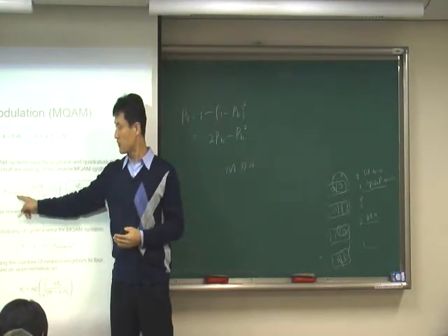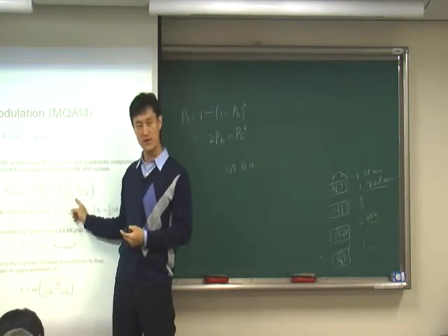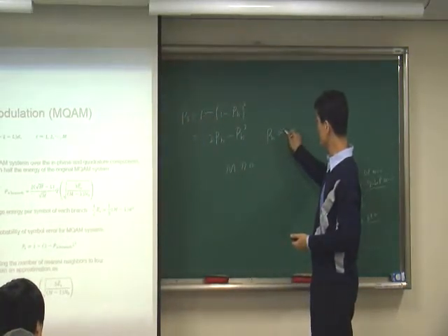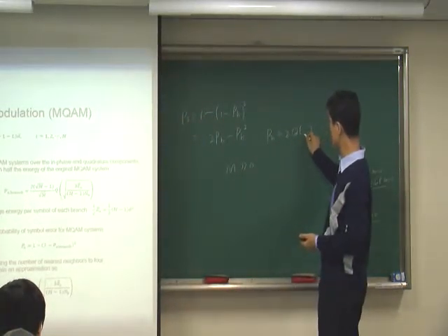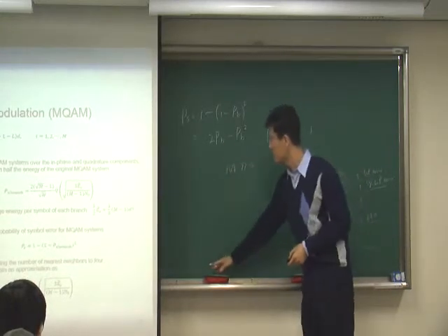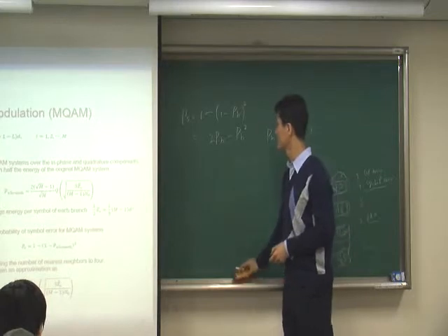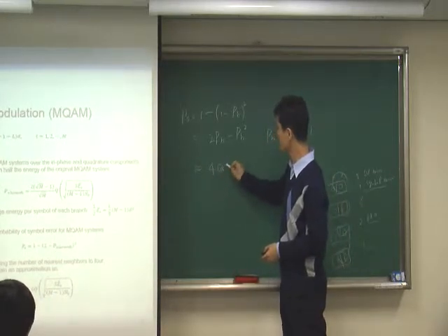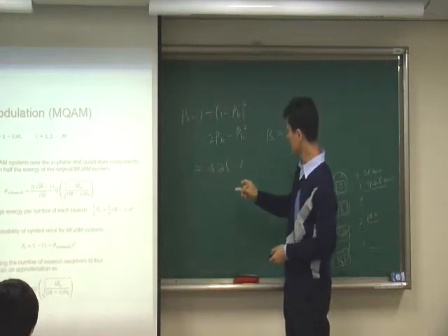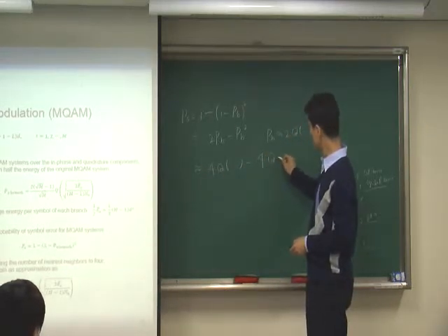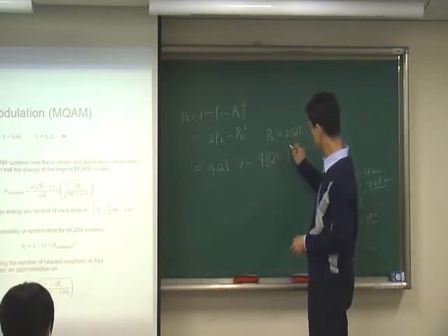So the original PB is 2 times Q function. So this original PB we can consider as 2 times the Q function. Okay, this Q function, so let's put that inside. Now then, we can approximate it as 4 times Q function, minus 4 times Q function square.